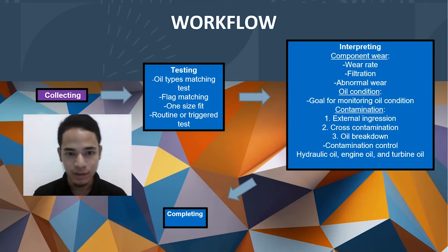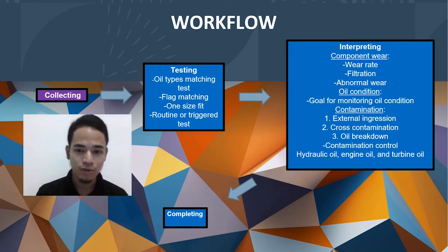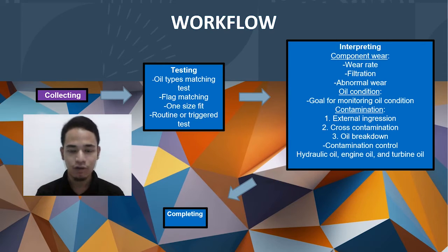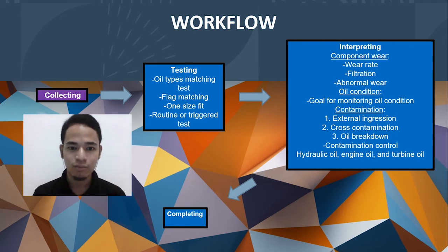Hello, my name is Anis Nafal. So right now, I would like to present about the workflow of this testing study of oil analysis. So the first step is collecting the oil sample for the oil components to be tested, usually in a commercial laboratory. And the second step is testing: matching testing to oil types and likely failure modes, and matching flagging to a corrective response plan.